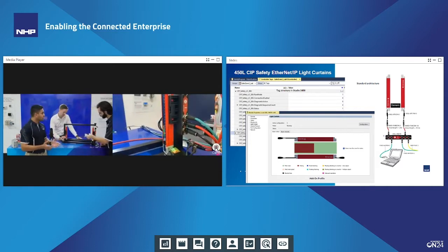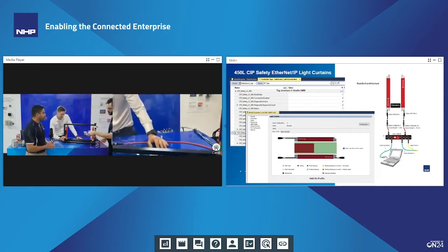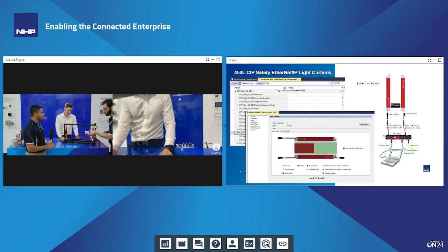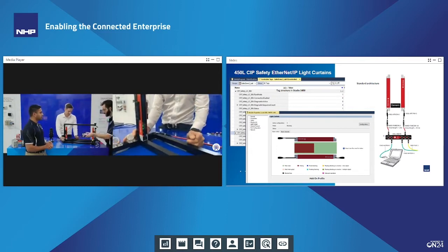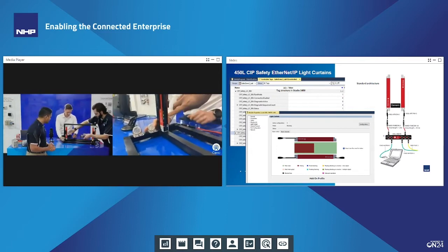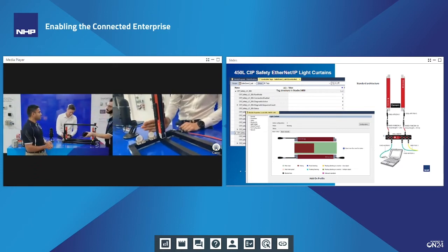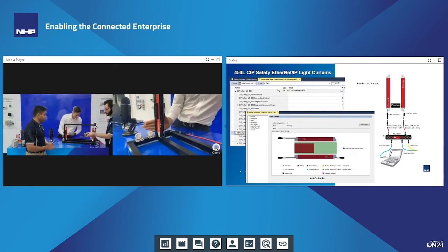One thing I might point out as well, Stefan, is that those greater than or equal to signs are on both light curtains. So it's not just on the transmitter or on the receiver, it's on both. So you look at both sticks in order to get that. Just to prove it, on the transmitter, it's those two just there. So we can tell by looking at both ends of the light curtain if they're aligned. Thanks, Dan. Thanks for adding that in.